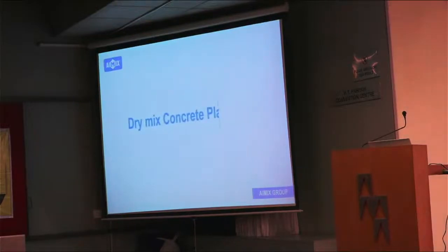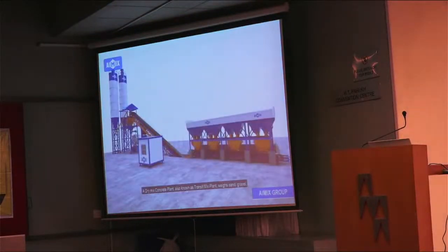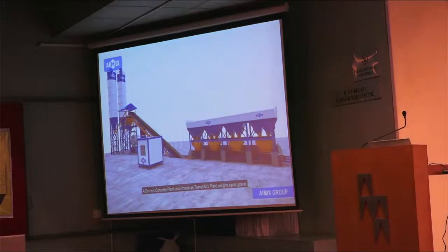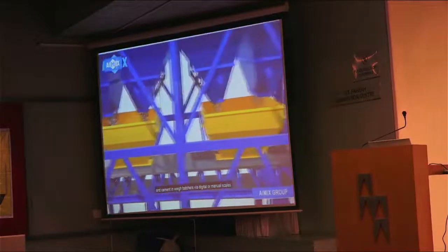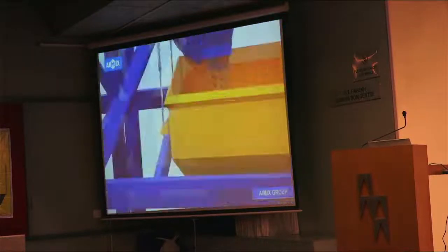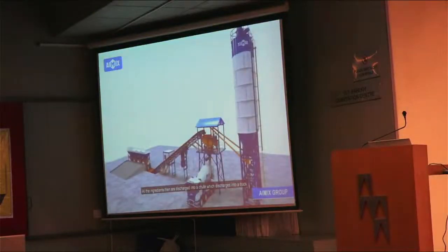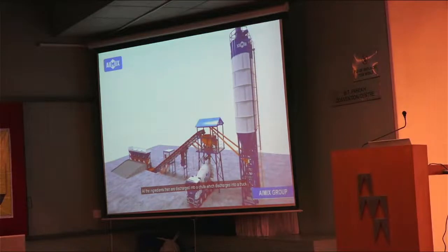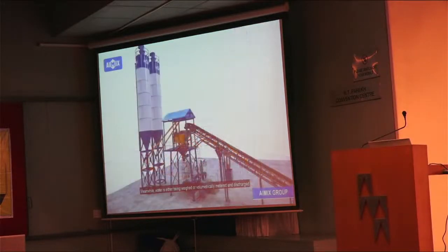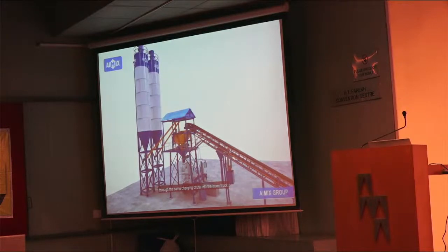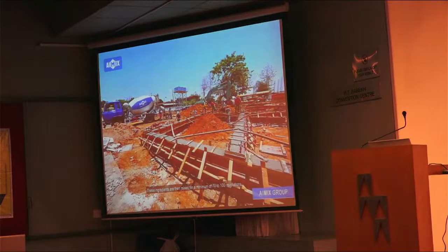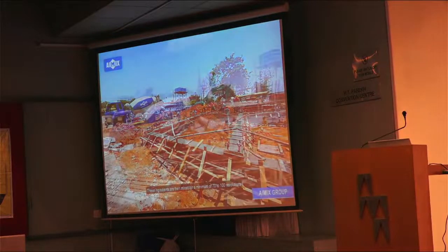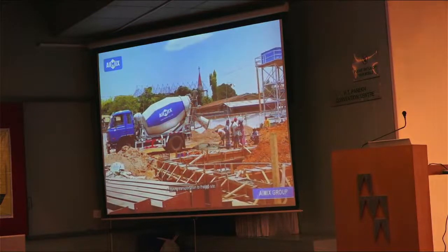Dry mix concrete plant. A dry mix concrete plant, also known as a transit mix plant, weighs sand, gravel, and cement in weight factors via digital or manual scales. All the ingredients are then discharged into a chute which discharges into a truck. Meanwhile, water is either weighed or volumetrically metered and discharged through the same charging chute into the mixer truck. These ingredients are then mixed for a minimum of 70 to 100 revolutions during transportation to the job site.